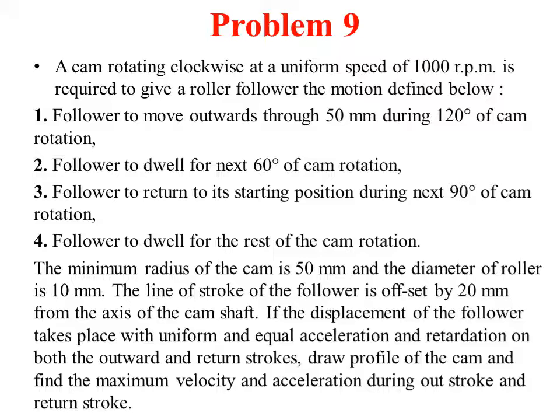Now join the points 1, 2, 3 and O dash, 1 dash, 2 dash and so on with center O, and make sure that these lines go beyond the base circle.